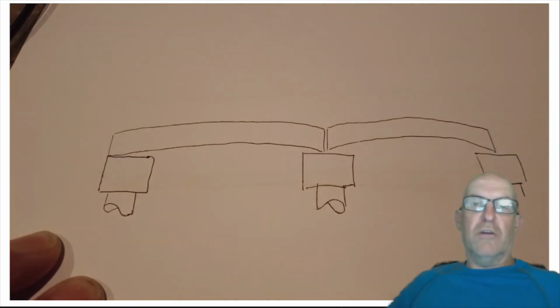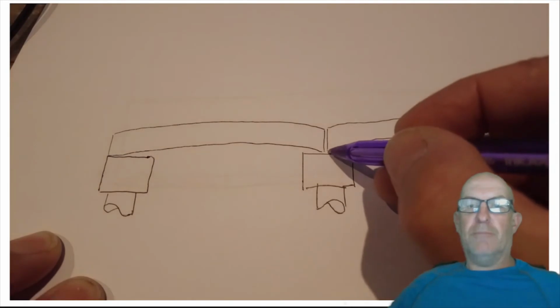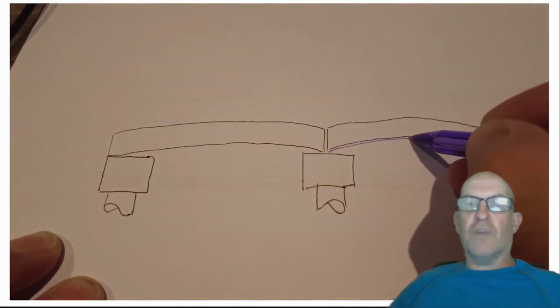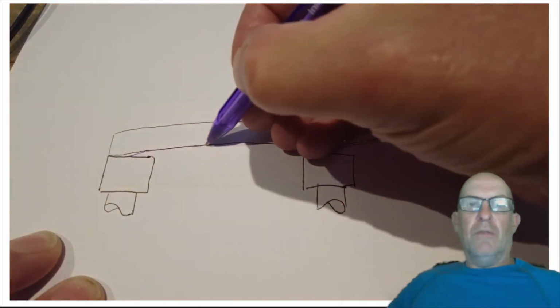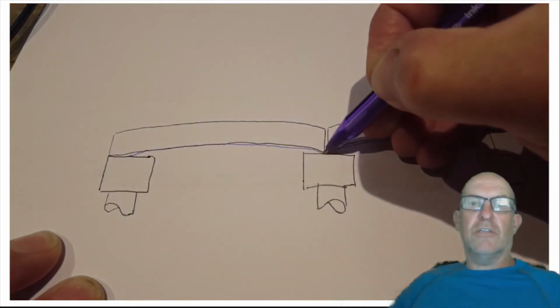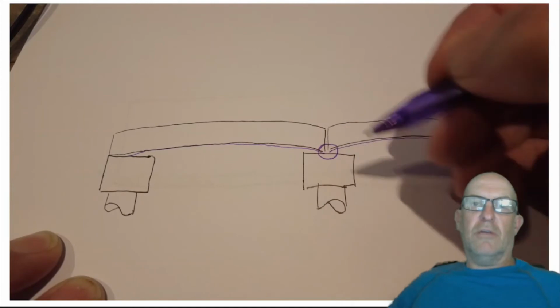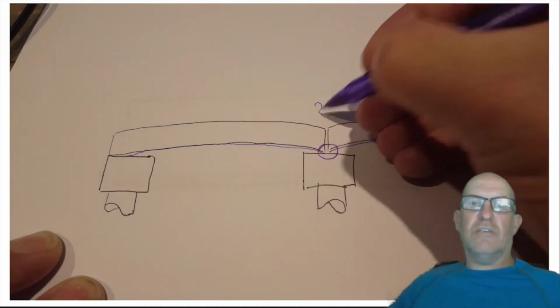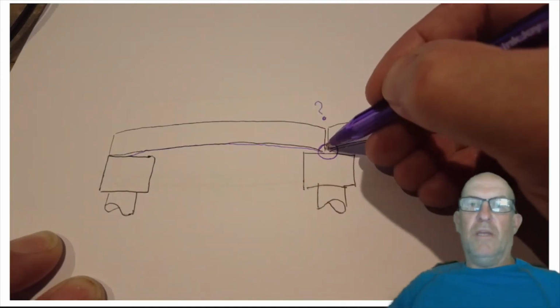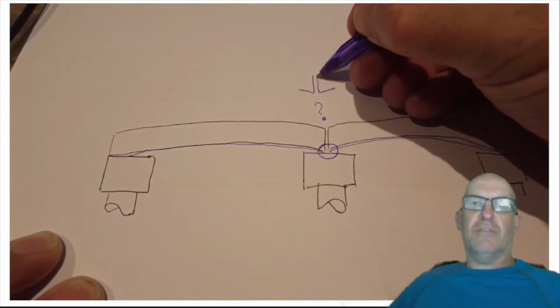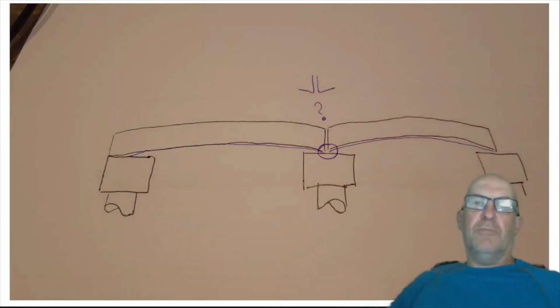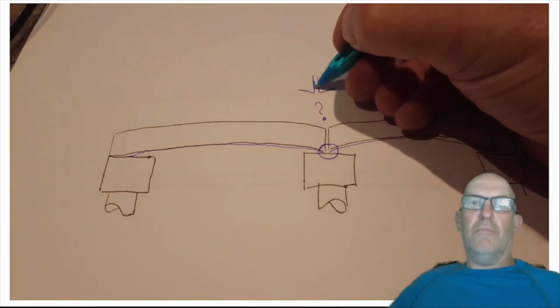Again, we could look at many different flooring types and structures, but here you can see using a bonded membrane that is actually cast into the underside of the slab. And looking at that junction there, that's always going to be a bit of a query point. We need to think, what can we do there? Or do we incorporate a kind of tail upstand system where possibly bonding them as they are located?